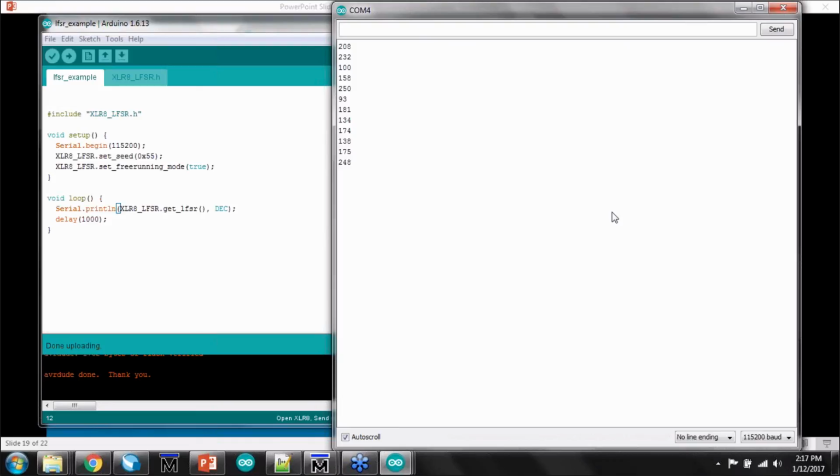But when it's free running, you may not access that register on the same interval every time you run a simulation or every time you use it for something. So you truly will get what appears to be a random set of numbers based on a given seed. But that's a really useful thing for being able to recreate scenarios or recreate the same sequence in the background, and if you're trying to isolate some kind of failure or isolate something with this sort of pseudo-random testing. Right.